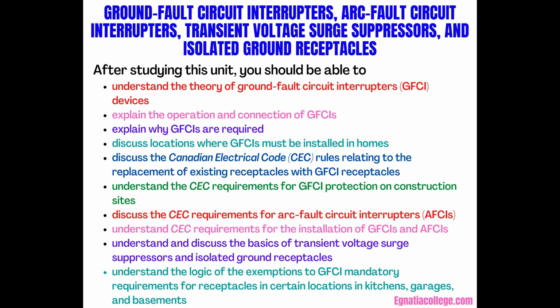Understand the CEC requirements for GFCI protection on construction sites. Understand the logic of the exemptions to GFCI mandatory requirements for receptacles in certain locations in kitchens, garages, and basements. Discuss the CEC requirements for arc fault circuit interrupters, AFCIs. Understand CEC requirements for the installation of GFCIs and AFCIs. Understand and discuss the basics of transient voltage surge suppressors and isolated ground receptacles.